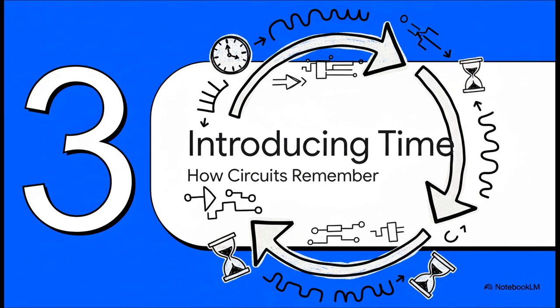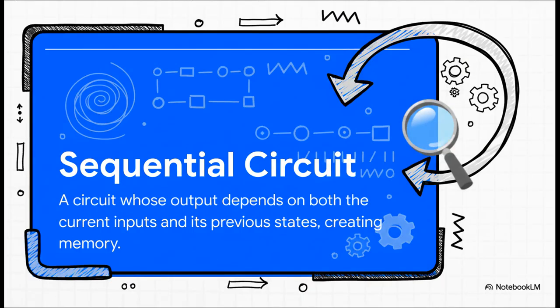And this is where everything changes. What happens if we take the output of one of these circuits and we feed it back into the input? Well, we create a loop. We introduce the element of time, of history, and just like that, we create memory. This feedback loop is the absolute secret sauce. You see, by taking a result from the past and literally feeding it back into the present calculation, the circuit suddenly has a state. It has a history. It's no longer just reacting to the now, it's evolving based on its own past. And that gives it the incredible ability to store information.